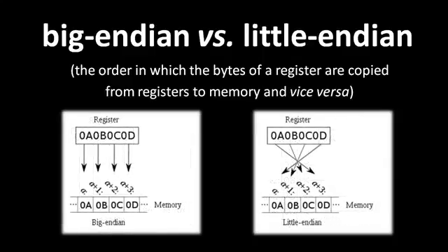But if we imagine memory as a horizontal array of bytes, the addresses must increase left to right unless we wish to go against all Western convention. Likewise, all Western convention tells us to write numbers with the most significant bytes on the left. So if we think of memory horizontally, it makes no sense whatsoever to use little endian. Unfortunately, for historical reasons relating to performance, Intel and some other CPU makers chose to use the little endian scheme. Those reasons no longer make sense with modern hardware, but the x86 architecture is still stuck with little endian byte ordering.